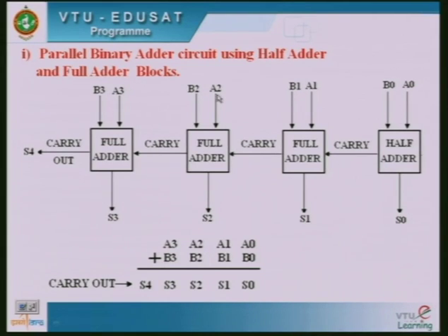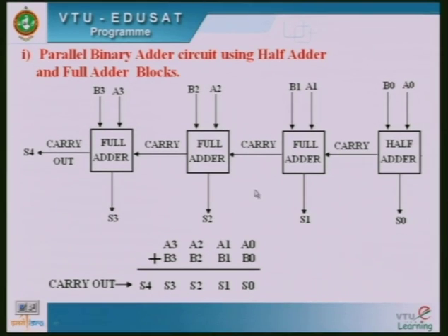In this stage, once again the A2 and B2 values are taken as input. Along with those 2 input values, the carry of the previous full adder stage is also taken into account, and all these 3 values are added, and the sum is noted as S2. Any carry generated is made available at the output of this stage, connected to the output terminal, and that carry out is made available as carry in for the next or last stage of this 4-bit adder circuit.